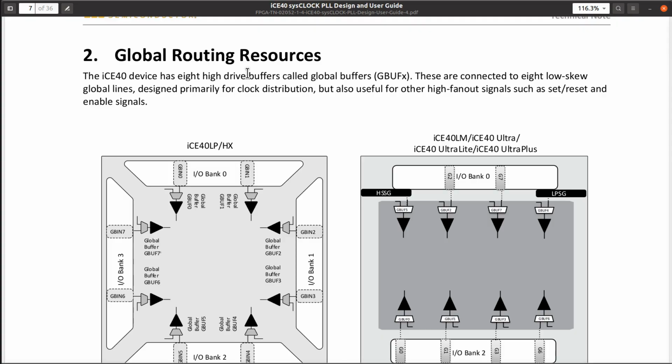The reason we have the PLL is so we can generate a free running clock frequency that 99.99999% of the time will be used to clock a synchronous design that you implement in your FPGA. So they've optimized it for the most likely use case. And that is, you want to generate a square wave with a 50-50 duty cycle that goes into a global